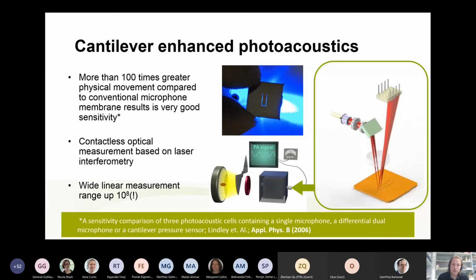So it's actually two things combined that make the good sensitivity. The thickness of the cantilever is in the micrometer scale, and the height and the width are in the millimeter scale. It sounds like it's not thick at all, but it's surprisingly robust thanks to properties of silicon.